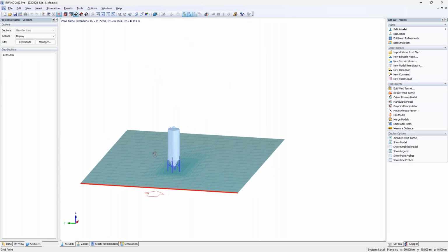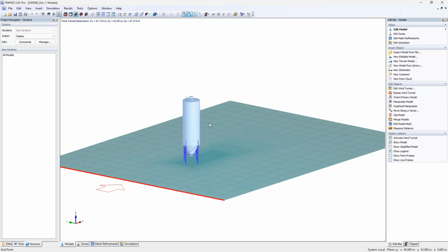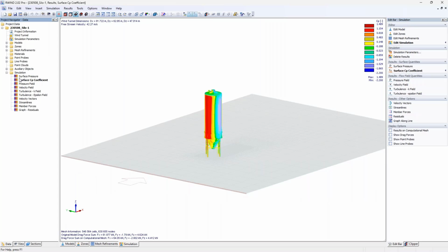So as told, we now have our one wind direction. Wind is blowing from the inlet to the outlet, interacting with the structure. Please take care, of course: our model is not moving at all, so it's most likely being infinitely stiff. But the volume elements with the CFD OpenFOAM calculation are, of course, interacting then with the pressure and our structure and giving us some simulation results. So the first results, which are available on the left side, are mentioned.